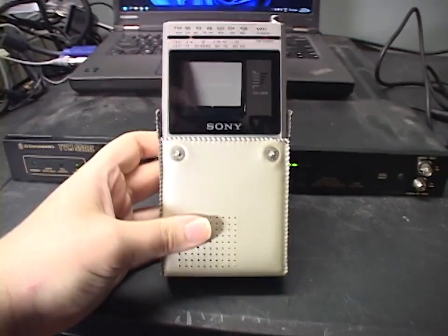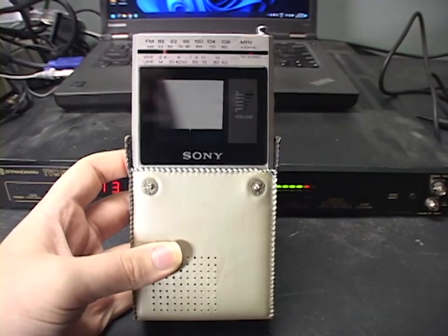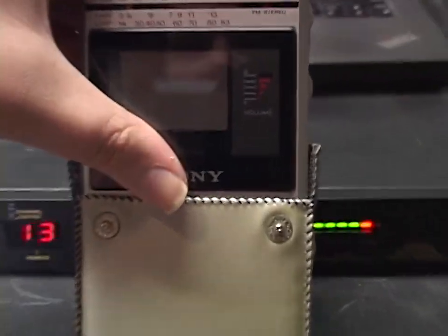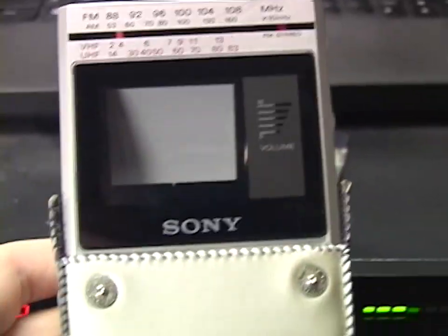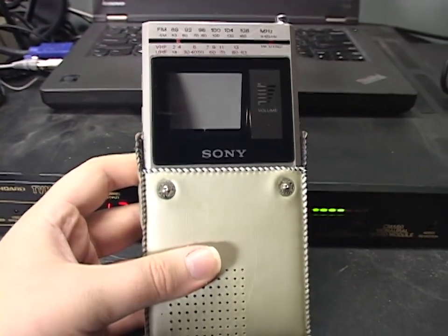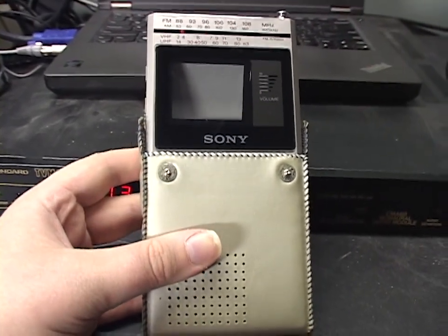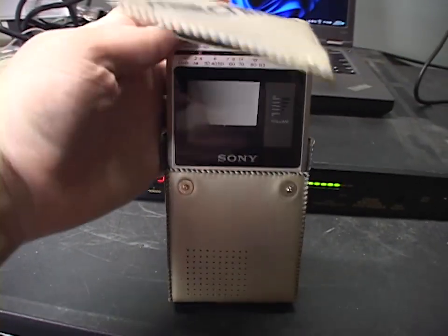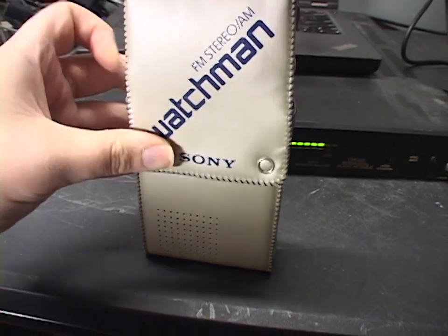Still turns on, still tunes in just fine. The volume knob of all things broke, so it's stuck at the bottom now. The little red scale moves up, but the actual potentiometer itself does not move. Or it is moving. I've been inside this thing. The potentiometer is moving, but it failed internally. So I've already got someone lined up who will pay me the cost of shipping to get this thing. So sad. I loved this thing. It's also the best transistor radio I've ever used.